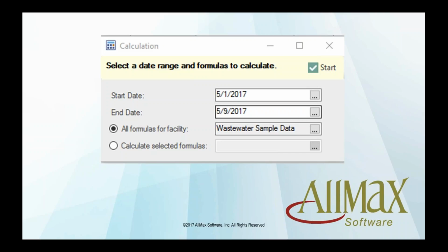So if you are having an issue right now with when you run calculations, say you have to run it 2 or 3 times to get the results that you're expecting, well, that's probably due to the fact that you have a calculation order problem. What can be done is going through your formulas and looking, well, what do I need to do this formula? If something is being done beforehand and it's not in the right order, you may have to adjust your formula order as need be. And again, like I said, we're going to cover that in the 3rd session.